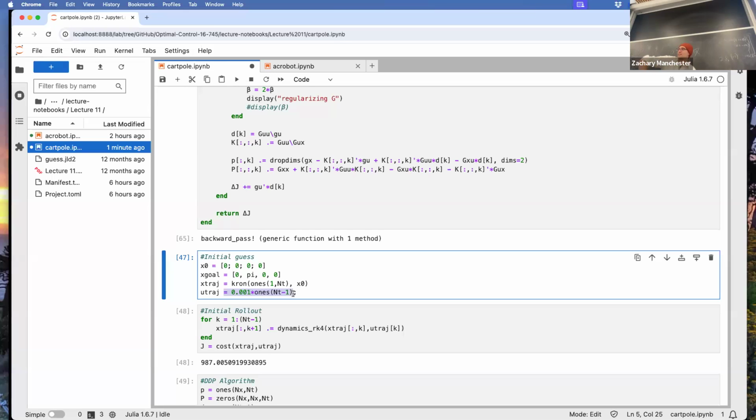Yeah, exactly. Basically if it's hanging straight down, there's this weird phenomenon where you want the gradient information to tell you to swing up, right? If you're sitting right here, there's an ambiguity of whether I swing left or swing right. And it doesn't matter. The problem's completely symmetric about going left or right at the initial conditions. So there's this annoying symmetry in the problem, which means the gradients are actually 0 if you're exactly at the bottom. So it's often a good idea to put a little bit of random noise on these things to avoid your gradients being 0 at weird configurations.